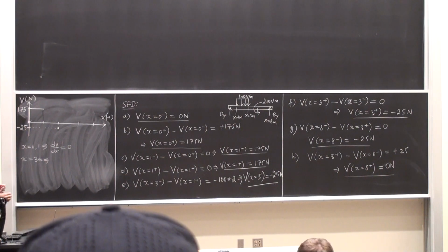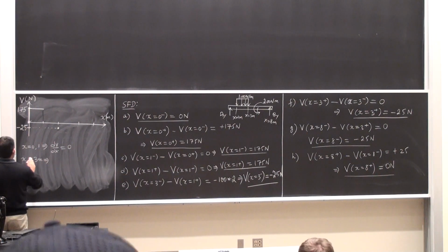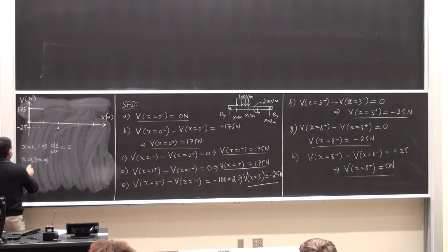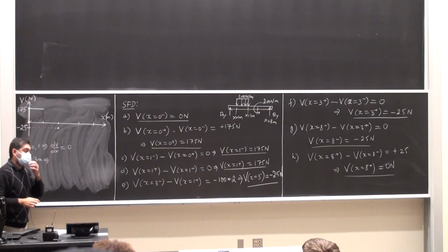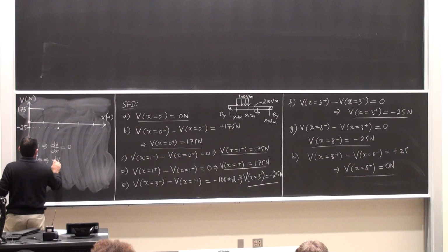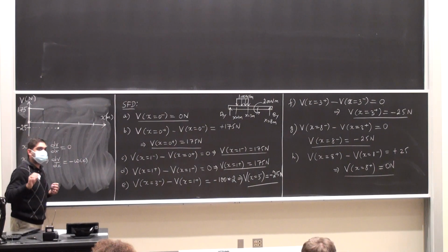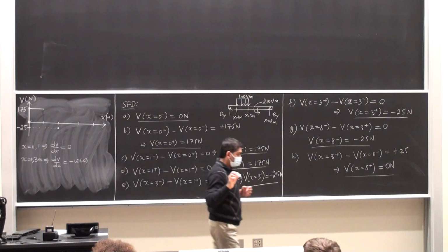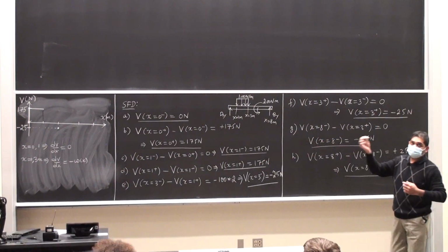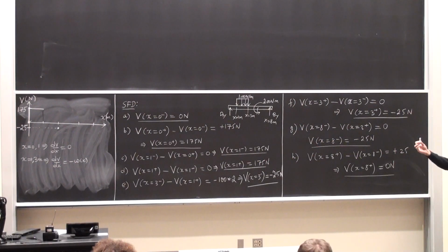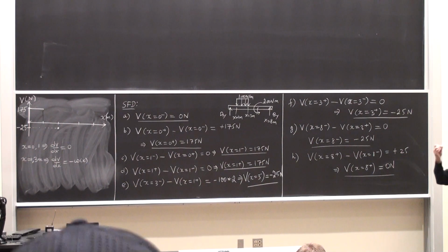Between 1 and 3, the slope of the shear force diagram is equal to the load intensity value, and there is actually a distributed load. What is the intensity of that load? The intensity of that load is constant.